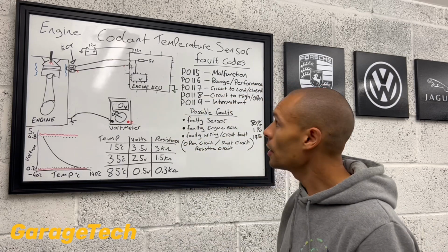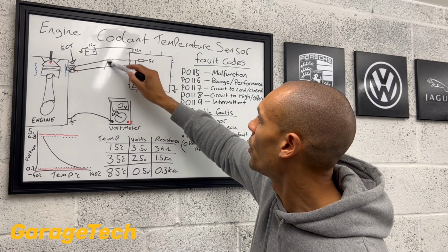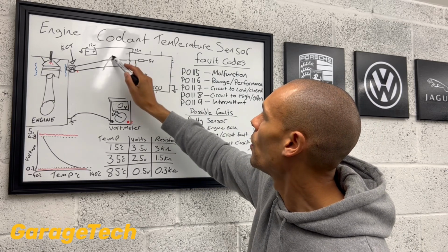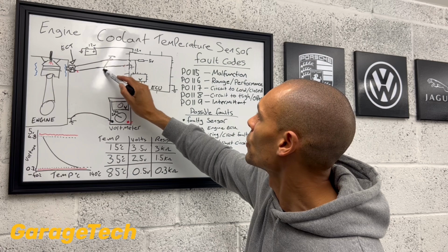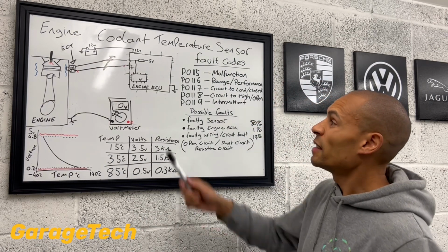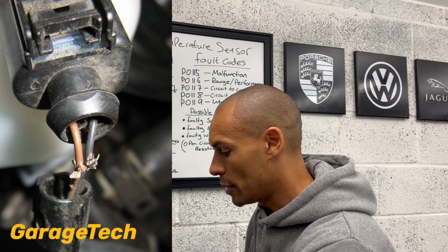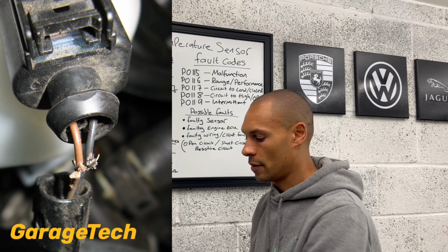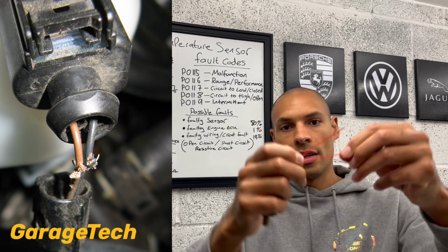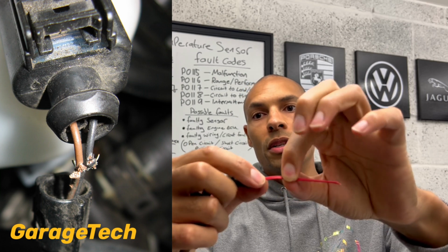But the chances are that you've probably got a chafe in the wire or something's happened in the wiring. I'll just use a demonstration of a screw. It's gone through, in this example, both the wires. So somewhere in that piece of wiring harness, I imagine that's the 2 wires. I've just opened them up now, but somewhere in there potentially it's chafed through and the 2 wires are potentially touching each other.